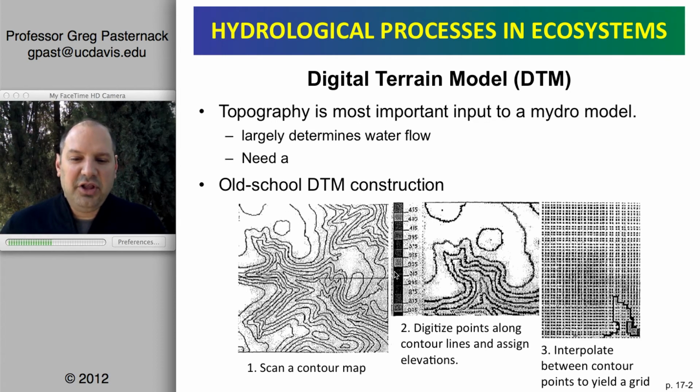On the left here is a black and white rendition of a contour map. Each line represents locations that have equal elevation, and as you go, your elevation is either going up or down. In this particular image, you don't know which way is up or down. Nothing in the image tells you that, but usually you have numbers or some other indication to provide that sense of height.